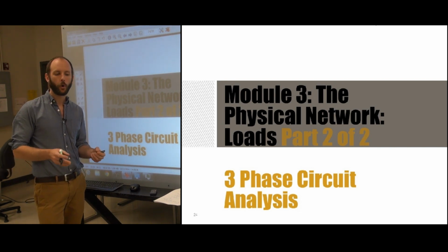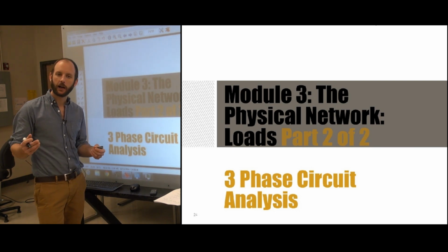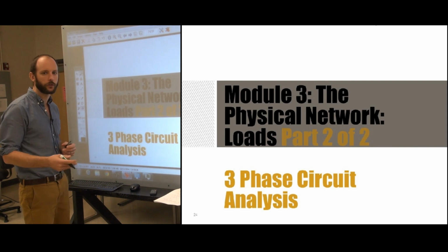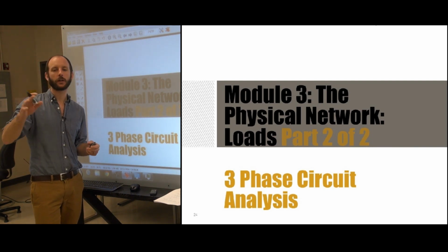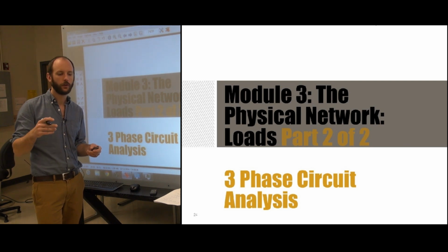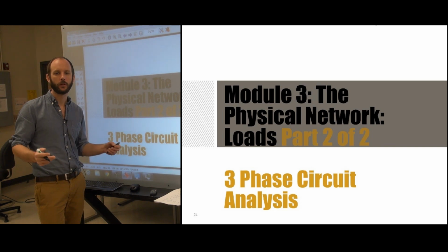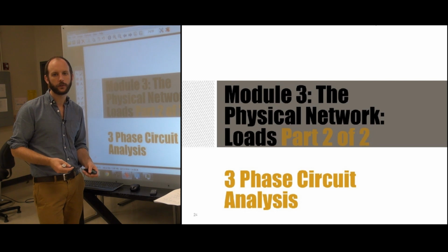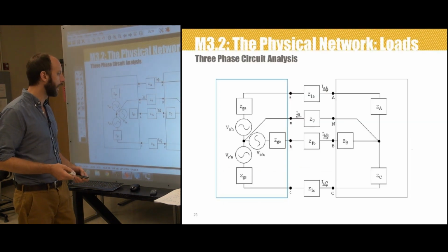So although Y and delta circuits can be analyzed using KVL, KCL, the Thevenin equivalent all the time, the easiest of them is the Y to Y. And so a common technique is to take whatever your circuit configuration is, whether it be Y delta, delta delta, delta Y, convert that over to a Y-Y network and then do the analysis. So obviously very important in three-phase circuit analysis is this technique of analyzing the most basic, or the Y-Y circuit.